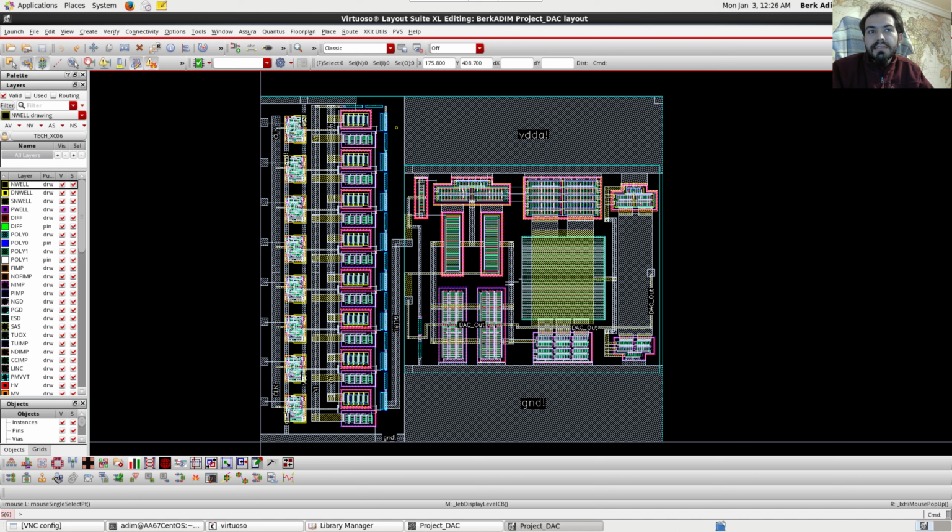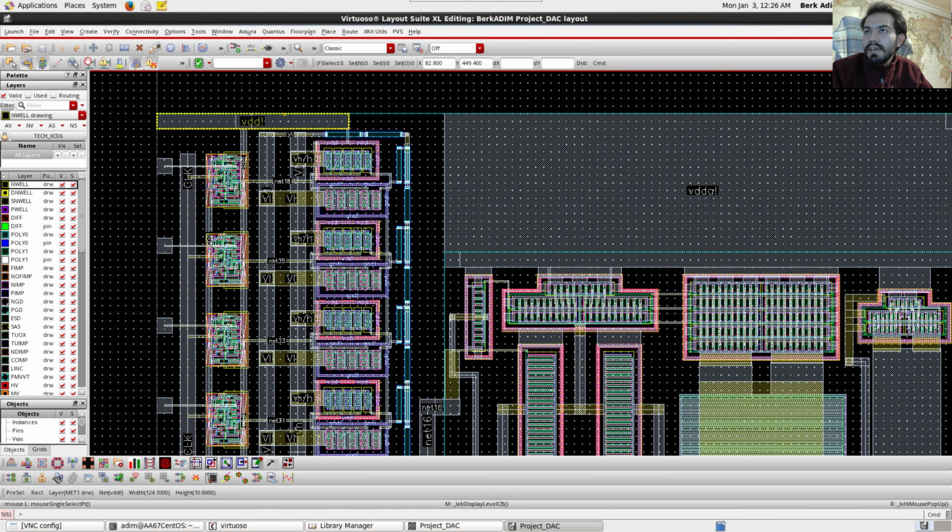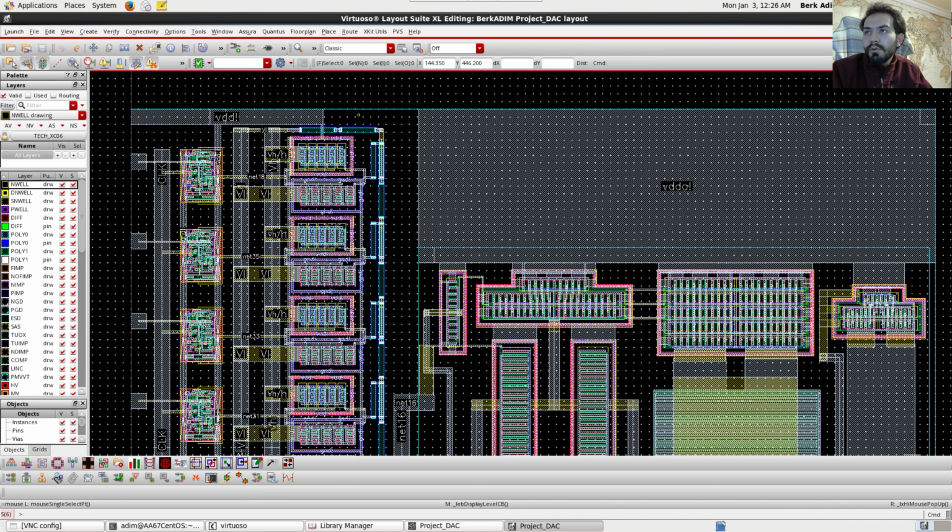Anyways, there are some important design considerations here actually. As you can see, we have split the voltage sources for the digital part of our circuit and the analog part. So when the digital part draws high currents from the supply in transient switching portions, the supply of our op-amp doesn't get affected, so the op-amp output doesn't get affected.